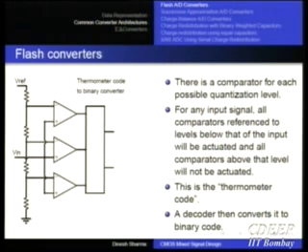So if I ask you to put your thinking caps on, and if I ask you what would be the equivalent of a flash D to A converter, an integrator is a sequential process by nature. So what would be a flash D to A converter? Just to make life simple, think of a current rather than a voltage. So this R has a series switch. You've converted each reference voltage to a current by using R by 2 and so on, and added a switch. So if you just add up all these currents, then you will get the corresponding equivalent of flash D to A, in terms of current.